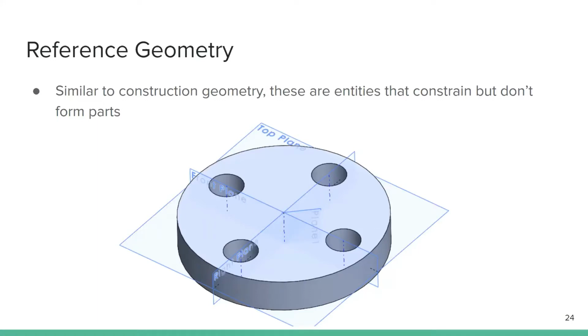So that's a big thing with reference geometry. If you make reference geometry referenced off of other geometry, then when you change the original geometry, the reference geometry will change too, just as any other feature in SolidWorks will. That's the beauty of SolidWorks. And then points, you can just click on a thing and make a point there, and you can use that for stuff.